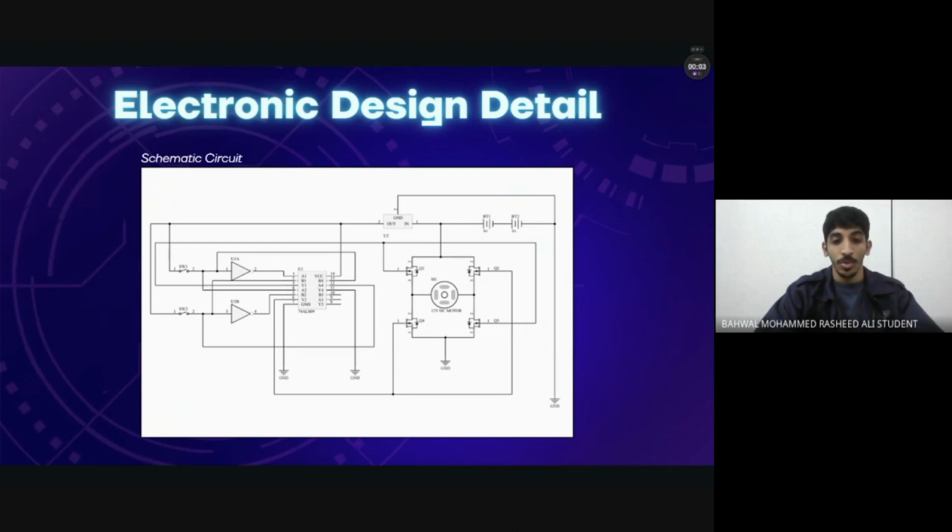We use two push buttons, switch 1 and switch 2, to control the direction of the motor. The signal from the switches goes through a NOT gate and a logic gate IC. Then the output controls 4 transistors arranged in an H bridge, which allows the motor to spin forward or reverse. The power is supplied by two 6-volt batteries in series, giving 12 volts to the motor. This setup is simple and doesn't need any programming, just logic control.